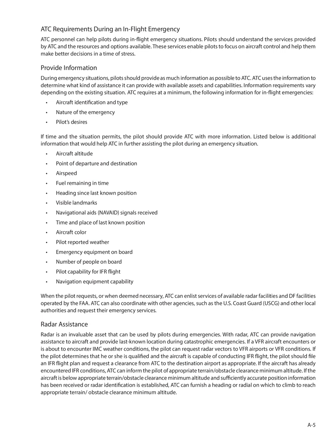If a VFR aircraft encounters or is about to encounter IMC weather conditions, the pilot can request radar vectors to VFR airports or VFR conditions. If the pilot determines that he or she is qualified and the aircraft is capable of conducting IFR flight, the pilot should file an IFR flight plan and request a clearance from ATC to the destination airport as appropriate.